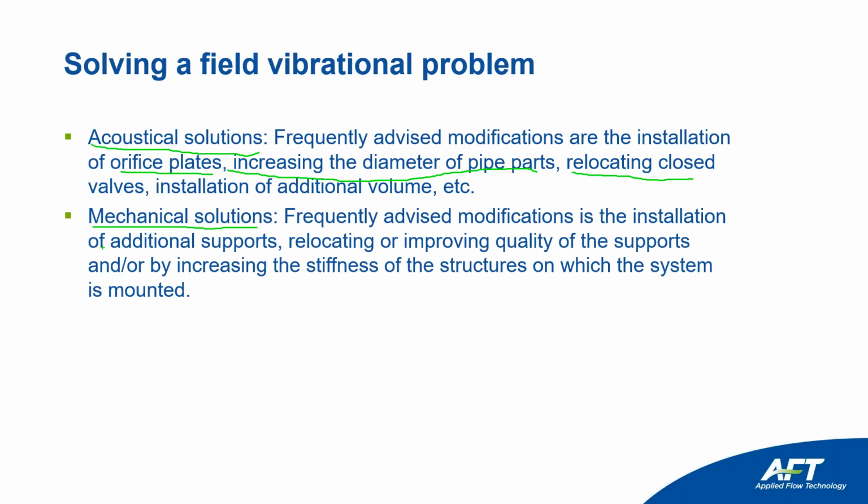frequently advised modifications are the installation of additional supports, relocating or improving the quality of the supports. Sometimes, like when using U-bolts, U-bolts do not constitute a dynamic restraint. So generally, if you're using U-bolts in a pipe that has dynamic problems, most probably you have to change them because they don't provide a dynamic restraint, and